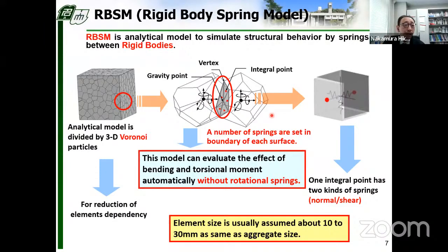RBSM is an analytical model that simulates structural behavior by springs between rigid bodies. And now the advantage is that it can be combined with Voronoi particles. That is a big jump to apply and extend the application of the RBSM to concrete structures.